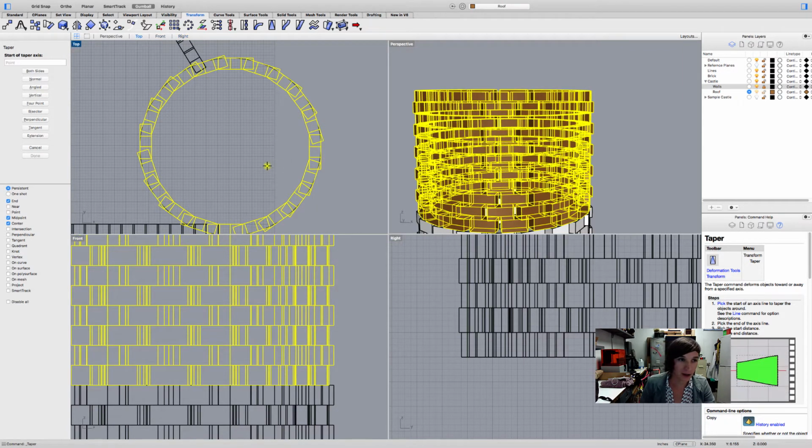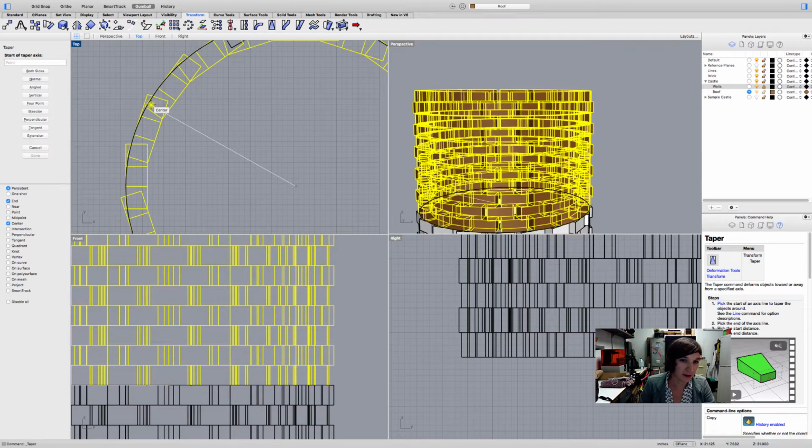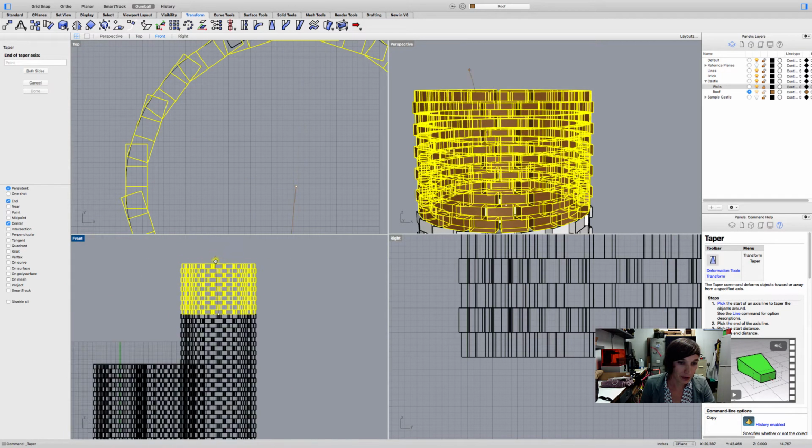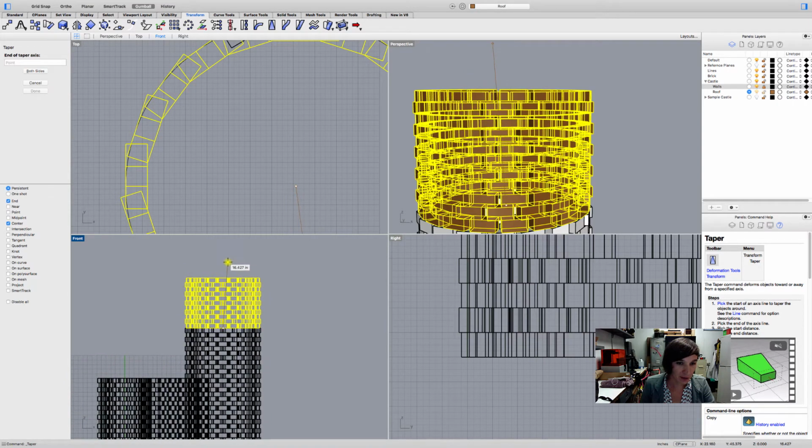Just follow that video along there if you would like. I got my center snap on, which is great because I'm going to select the center of that. Now the top or the end of it is going to be up here somewhere. I'm just going to hold shift. Again, shift will keep it going straight.